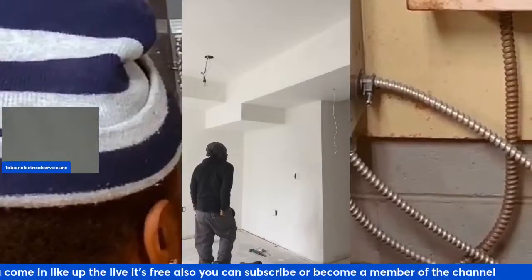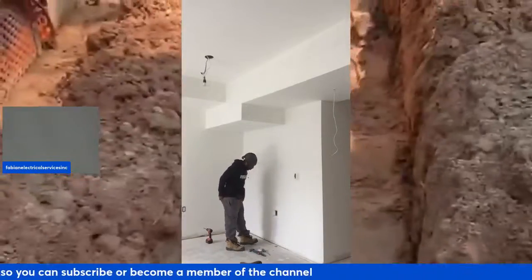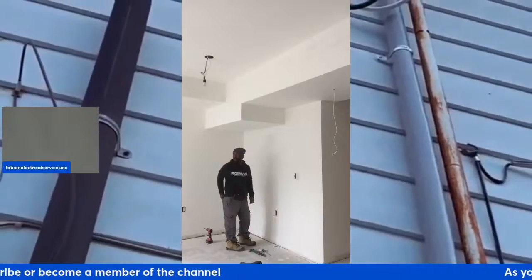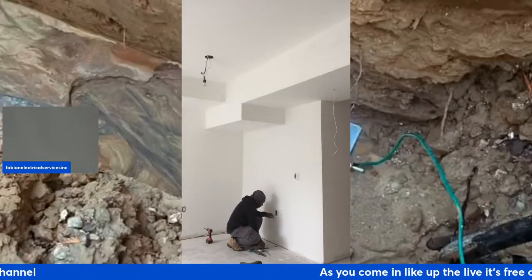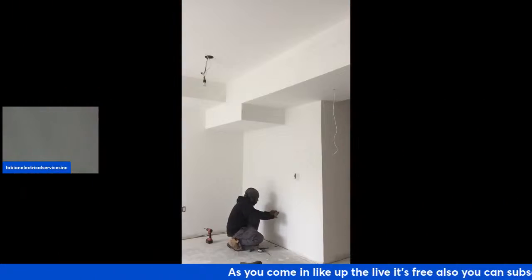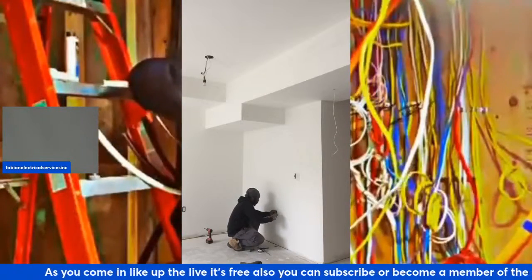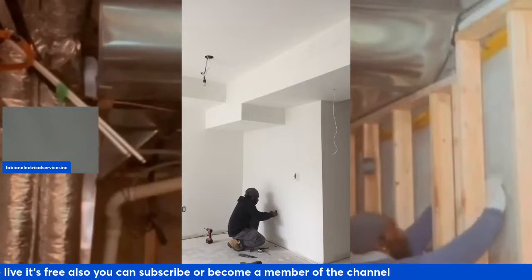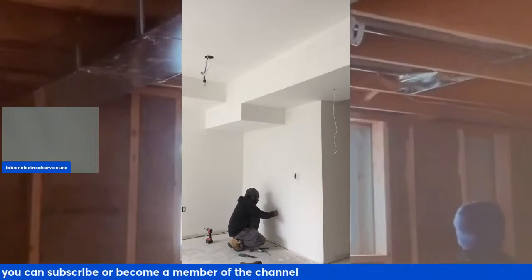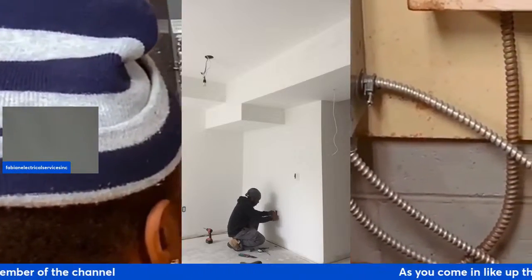The only way it's not is if it comes with an end where it's going to require a direct connection. I don't believe it needs an arc fault then. Even your microwave inside of your kitchen takes an arc fault also, if it's not a direct connection. So these are things that will require the arc fault protection.